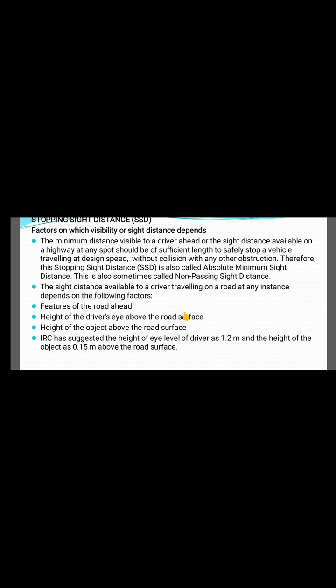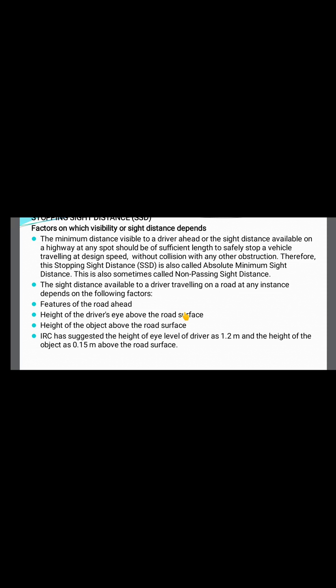For this, they have specified that the eye level of the driver is at a height of 1.2 meter above the ground, and the height of the object above the ground level is 0.15 meter. That is what the IRC has suggested.